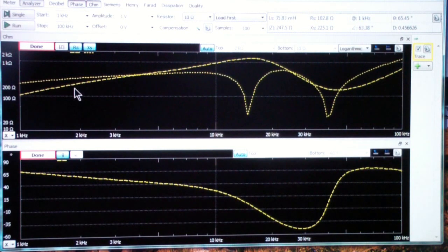And speaking of the resistance, you may wonder, why isn't the resistance just a straight line? Well, the fact is that the resistance, because it includes eddy currents and other things that are reflected as additional resistance, the actual resistance of a transformer, primary or secondary, over a frequency range is not a constant because of all of the parasitics.